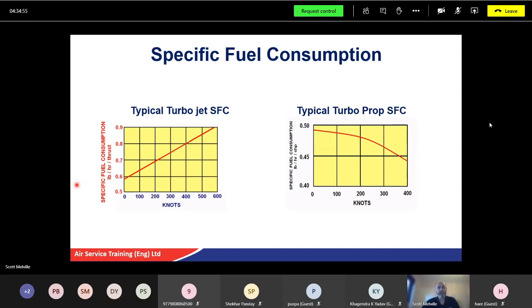It is the size of the propeller, the weight of the propeller, the aerodynamics of the propeller that makes it more efficient. By using a bypass principle, high thermal and propulsive efficiencies can be effectively combined by bypassing a proportion of the LP air. In other words, basically turning your fan into a propeller, sort of a rough equivalent.